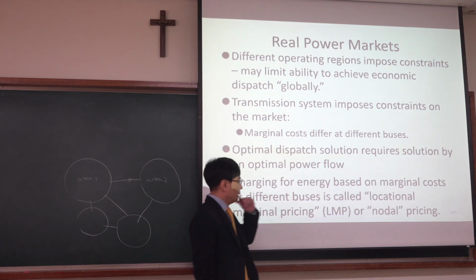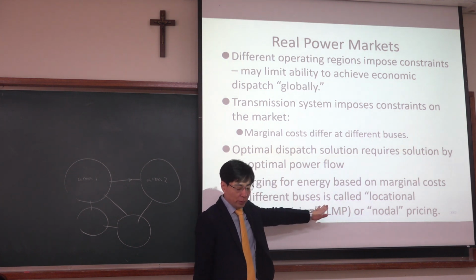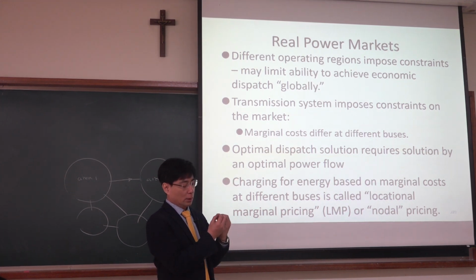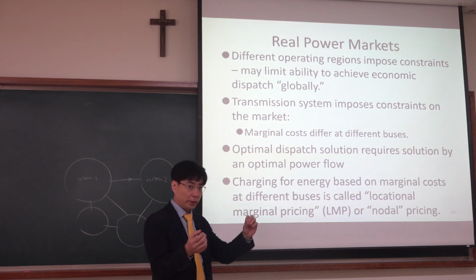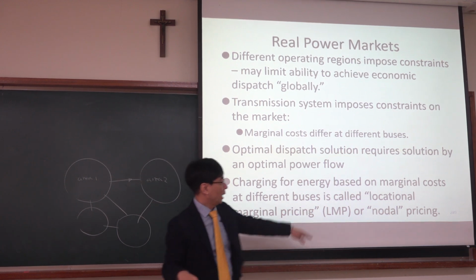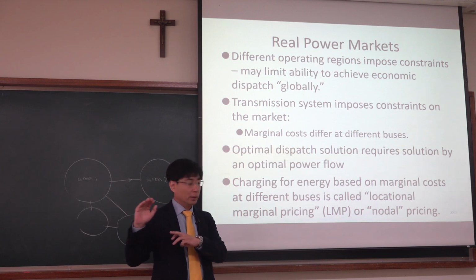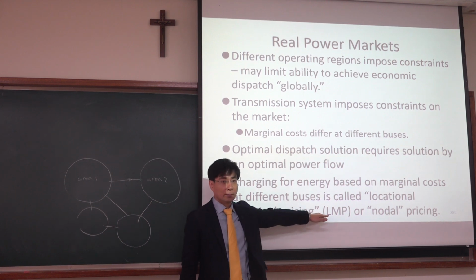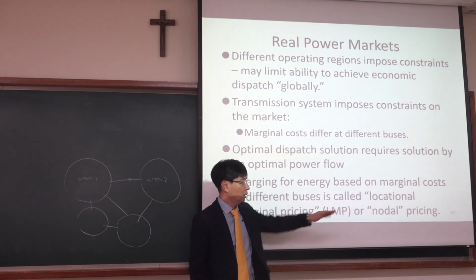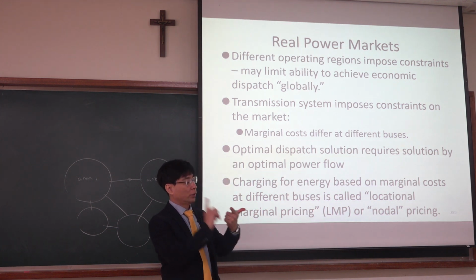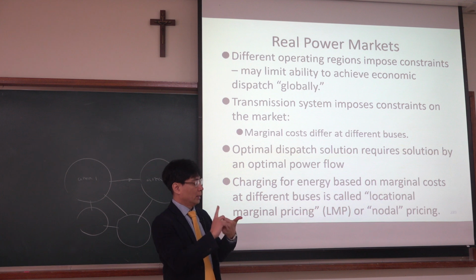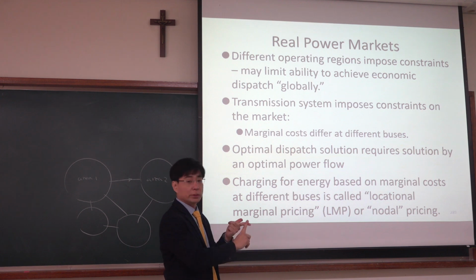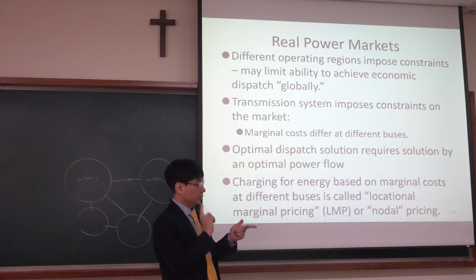So, by the way, when you compute LMP, when you solve optimal power flow and know all the dual variables of the generators and transmission line, you can compute LMP from the dual variables. But please do not confuse that dual variables are not exactly the same as LMP. Because LMP includes the generation cost and the transmission. LMP comes from the generation cost, and the generator has its limit, and also it needs to consider the transmission limit, another constraint, and also power losses.